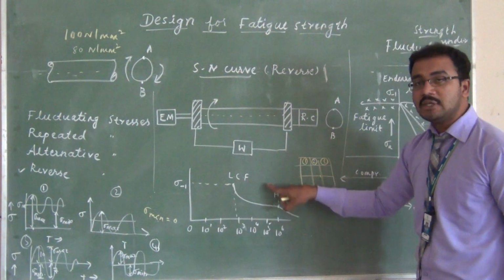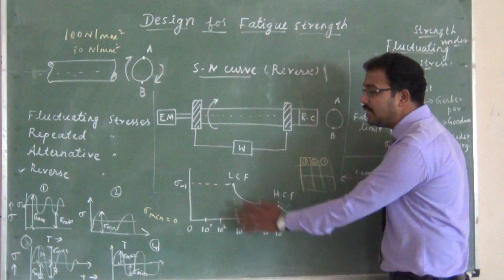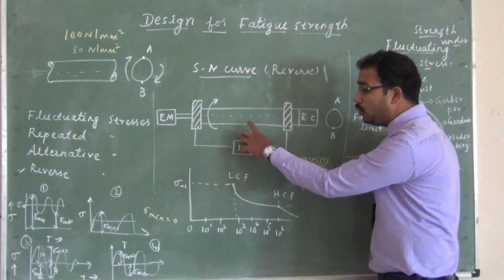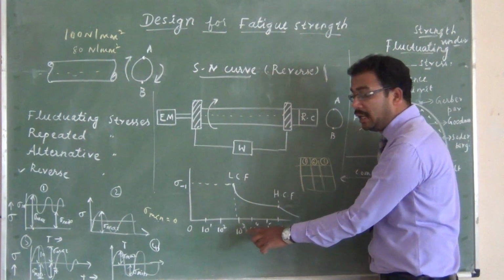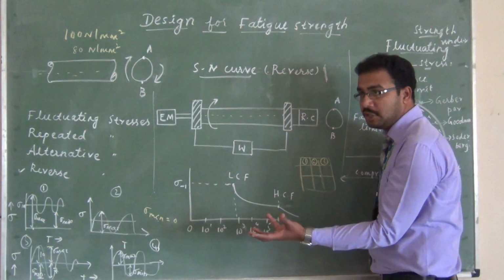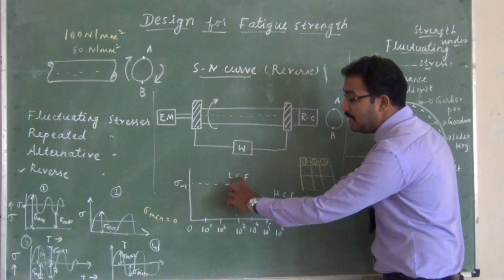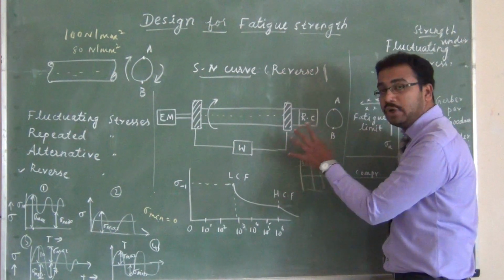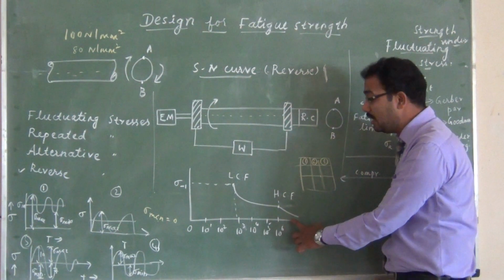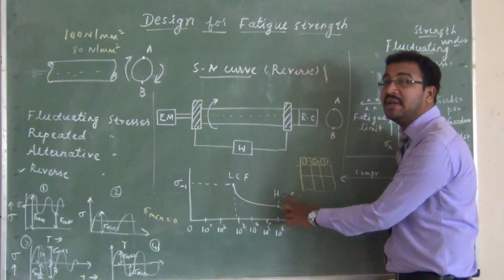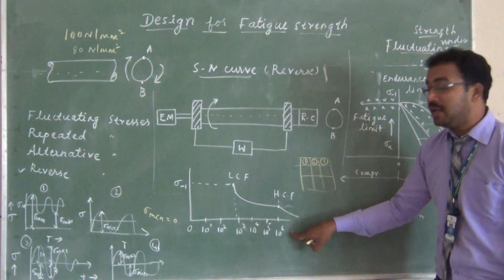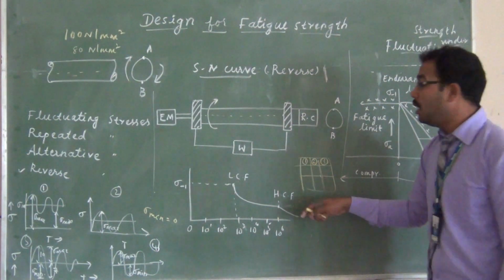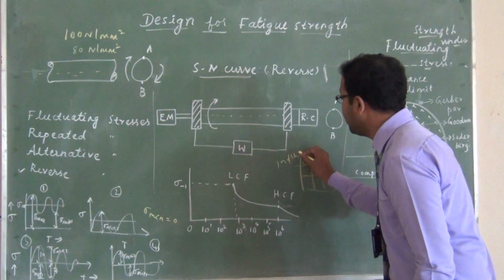It reaches a very important point called the high cycle fatigue. So the purpose of this logarithmic graph is that it is clear that in any application, if the material is able to rotate without any damage or problems or vibration till 10 power 3, then I can recommend it for a safe design. With the same material, if it is able to rotate till 10 power 6 cycles, then it is called high cycle fatigue. It means I can always refer to a material which easily crosses 10 power 6 cycles without any damage, and that can be recommended for infinite life.